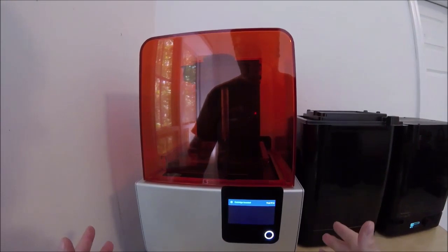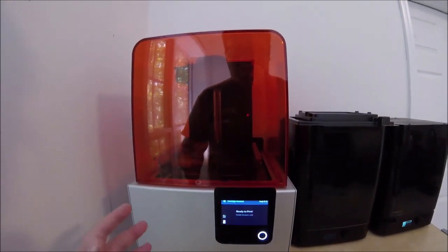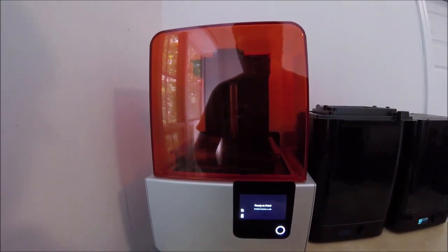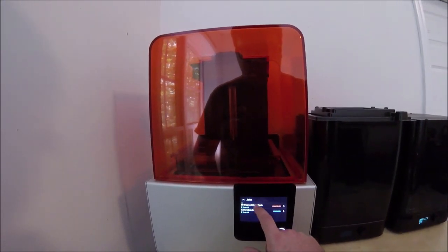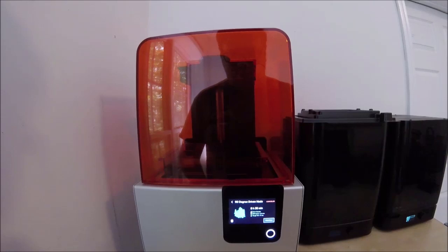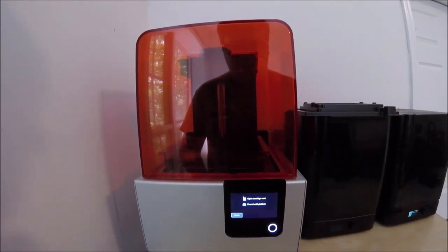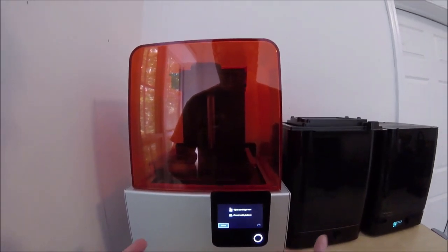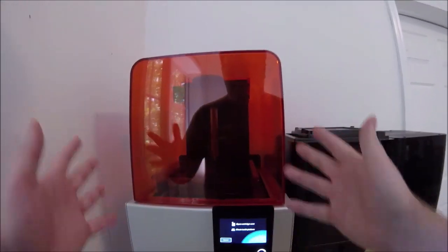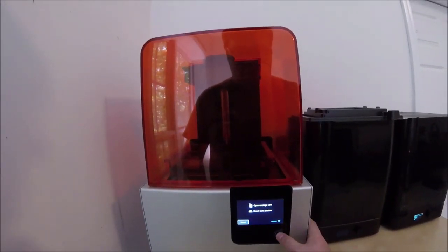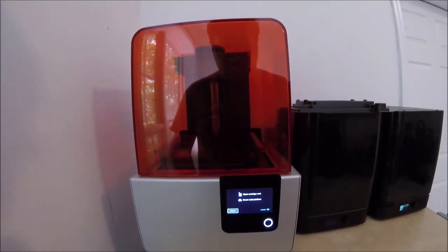Now the printer is assembled and ready to print, so all we have to do is select the model we want to print, the PreForm file we sent over earlier. This is the 90-degree driven node, so we're going to select that print, then click Print Now. The printer is going to initialize. Right now it's just reminding us to make sure the vent cap is open, which we just did, and to make sure that there's a build platform in the printer, which there is. So we're sure of all of that, and we're going to push Confirm.